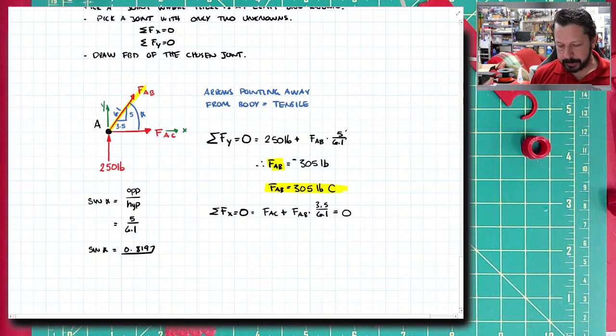So this is where you have to decide what you're going to do with tension and compression. And this is why I decide that I'm always going to draw all my arrows in tension. That way I know that compression numbers are always going to be negative values, and tension numbers are always going to be positive values, but you do have to get these arrows the right way in your mind. You don't necessarily have to redraw them on paper, but if that helps you, maybe you should do that. But you just need a system for you that keeps these arrows in positive and negative related to tension and compression all consistent. As long as it's all consistent, you'll be all right.